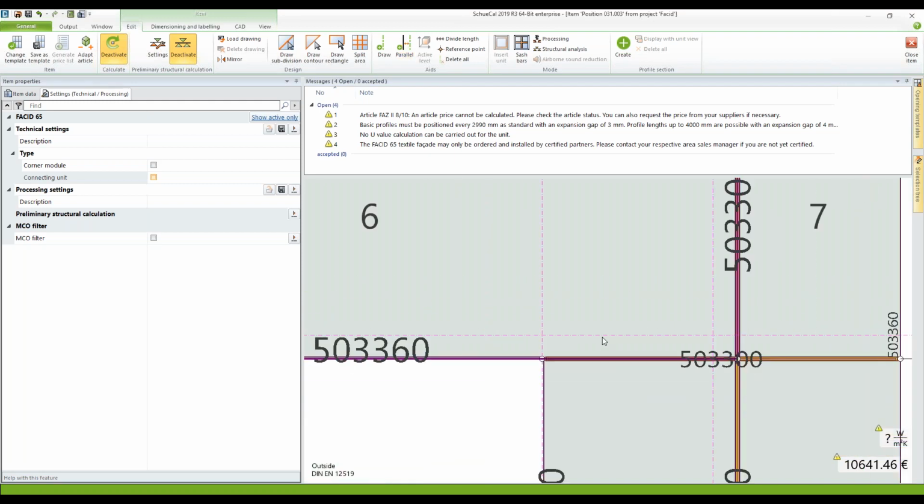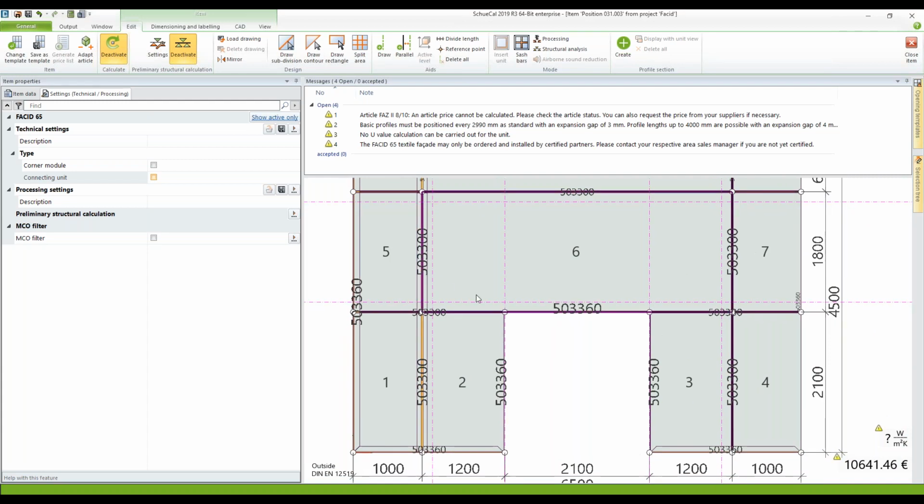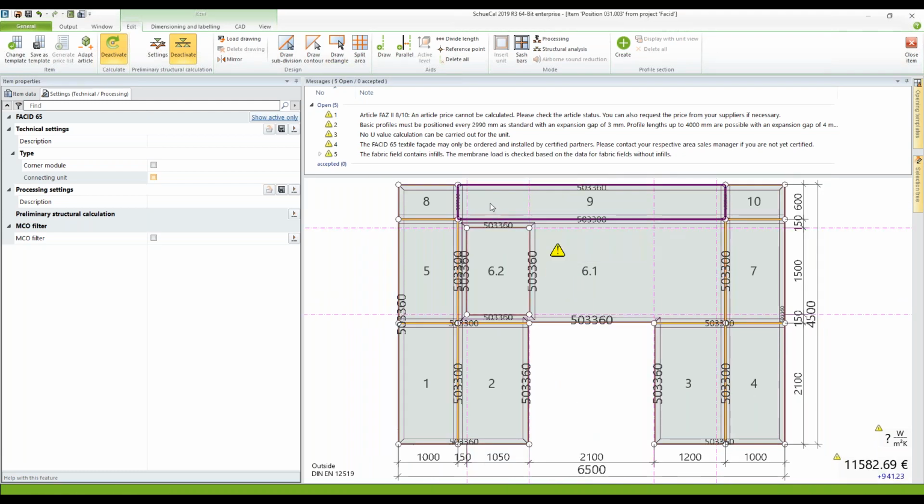So what we have achieved is this kind of construction of the help lines here, and then it's quite simple to use the rectangle function, snap the first point, snap the last point, and all of a sudden you get the profiles here, which are shimmering through the fabric now. Go here, go there, click on there.